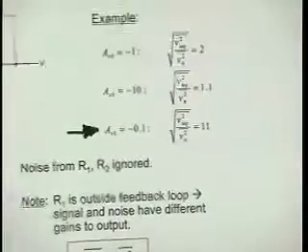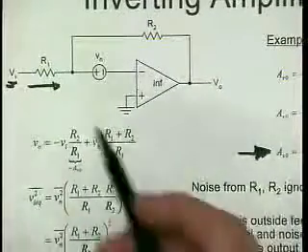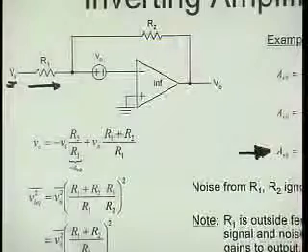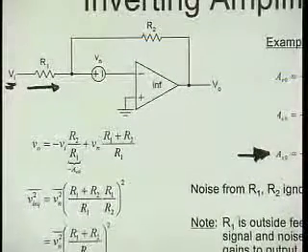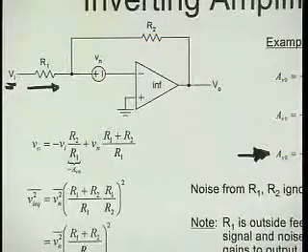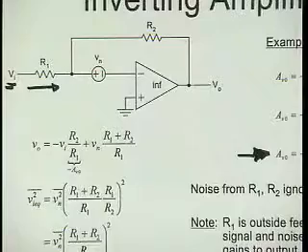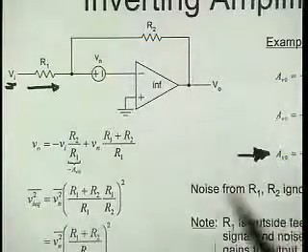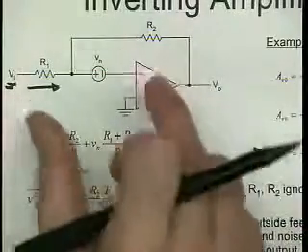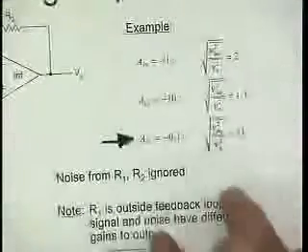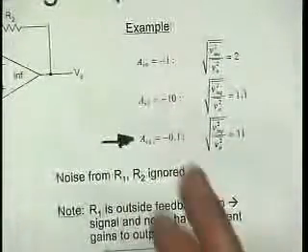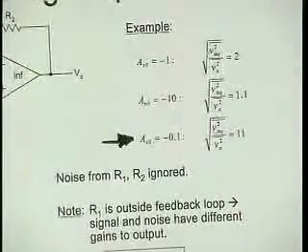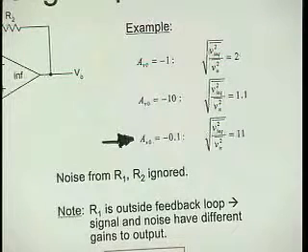Well, I think I've already alluded to that we are not going to very often use resistive feedback networks, but we are going to use instead capacitive feedback networks. And then things are a little different, and we actually can get significant factors where the noise is really enhanced significantly because of this effect here.